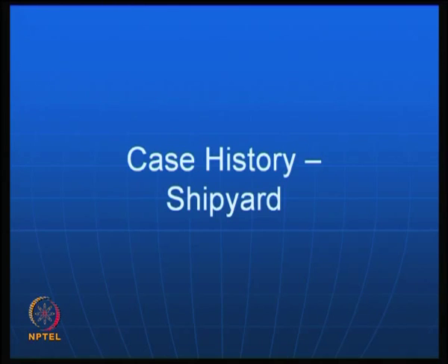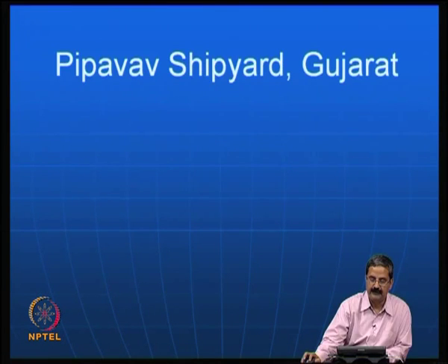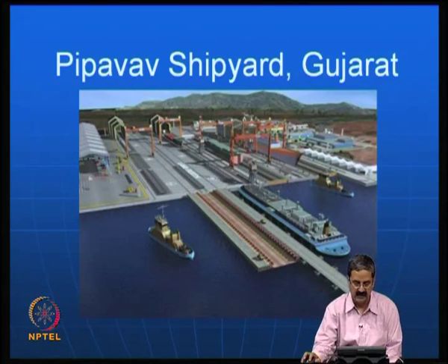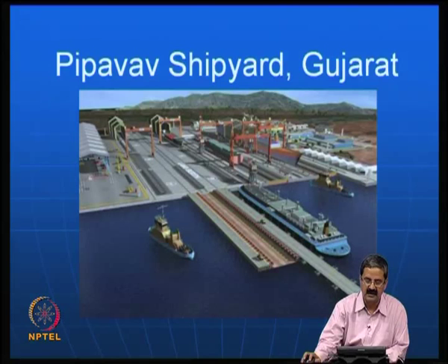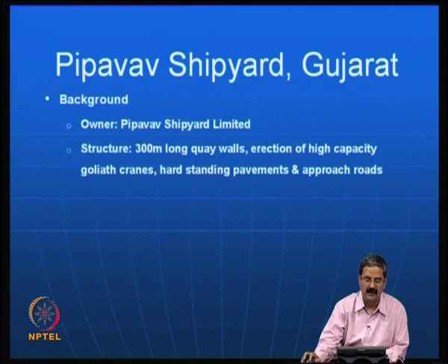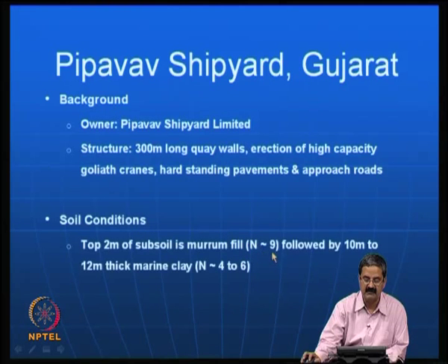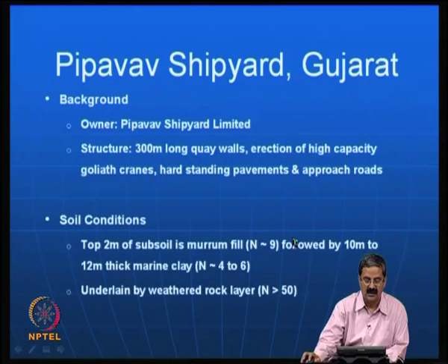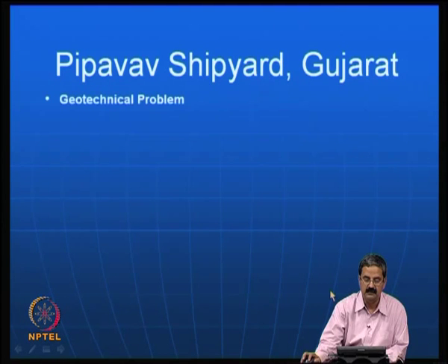There is another case study that we have, and it is again in Pipavav shipyard, Gujarat. As I just mentioned, they have been very kind to spare some of the information here. Again you have a quay wall here, and the soil conditions: the SPT value is very low, around 9, and then it has a marine clay of 4 to 6, so you can see that it is quite tough. And then, fortunately, you have weathered rock at the bottom.